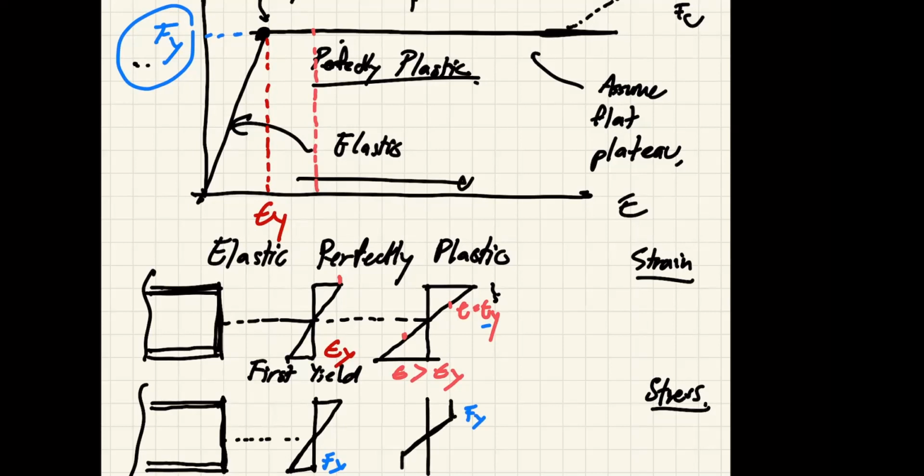So your stress distribution looks like this. You see, it's still Fy, but it yields more. Now the yielding of your cross section just creeps down from the outermost layer that you generally learn from your mechanics of materials. That's where your maximum stress occurs, right? But because we use this kind of stress-strain relationship, we now have the stress diagram that looks like this.